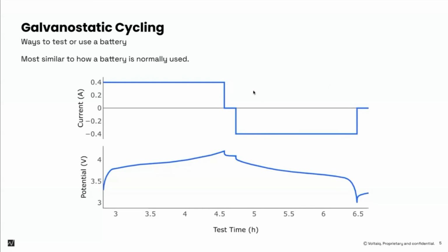Now, there was a question that just came in the chat about how you calculate charge and discharge capacities. So it's usually the integration of the current right here underneath in time, and you get the amount of capacity that has been passed by that system, and you can compare that from charge and discharge. And when Stephen gets to talking, he'll talk a lot about how NOVONIX has really high precision equipment to be able to accurately measure those and measure the difference between charge and discharge, right? Which a lot of times we call Coulombic efficiency, but there's a lot of additional information that we can get out of those types of measurements as well.